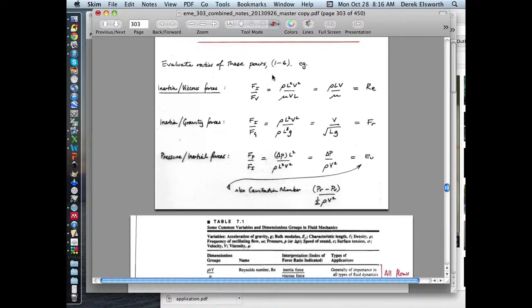Reynolds number is of absolute importance for kinematic similitude. The flow patterns around the structure look identical at the same Reynolds number. And if you're looking at a closed pipe or an open pipe, then these would be the appropriate numbers to use. So you get some feel for these. You can use the Buckingham Pi theorem to get these relationships, or you can also kind of guess them with some intuition, and they'll probably be something like this.